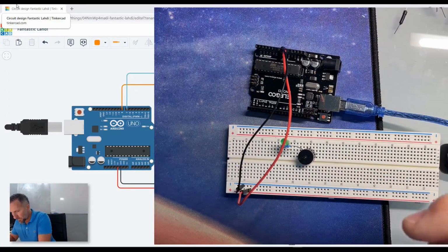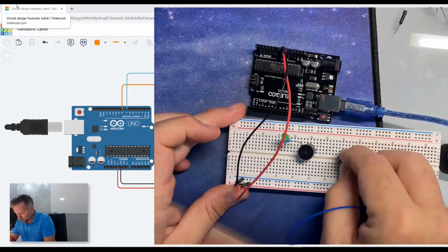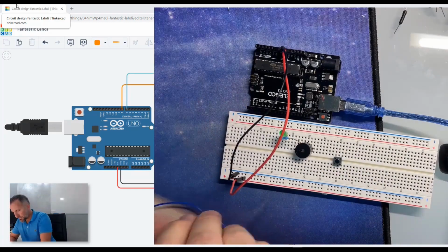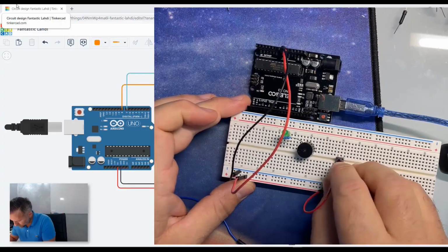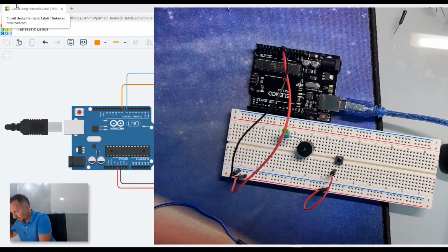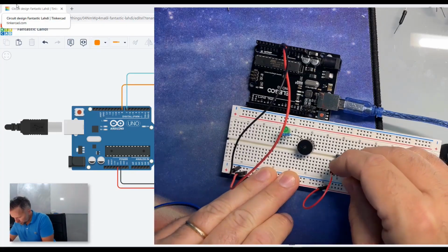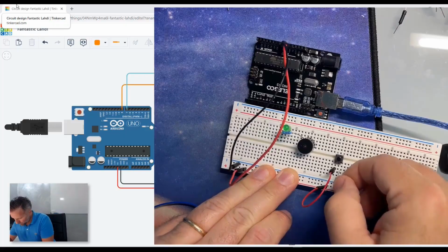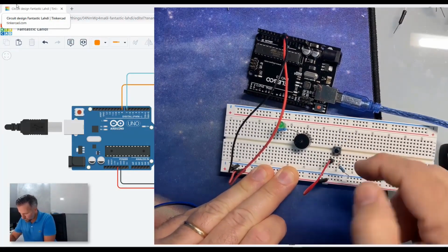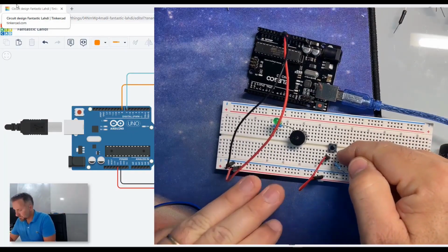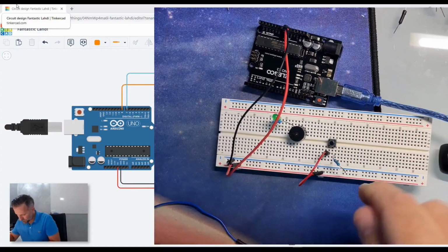Then, we also take a button. To activate the circuit, the button directly takes 5 volts from one side, and the other side we refer to as ground. In this way, bringing one end, we place it, let's say, on the same side of the button, thus already connected to the 5 volts. So at this point, we will have a stable electrical potential of 5 volts, referred to ground through this 1K resistor.